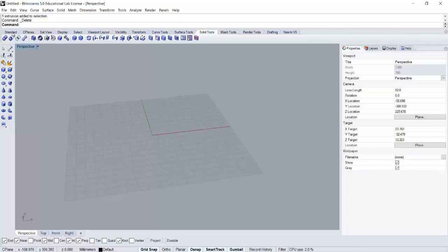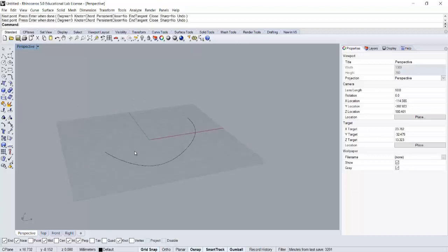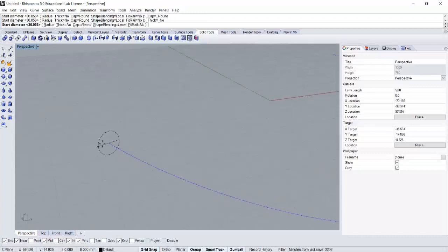Now this relies on having a curve in to start with, so let's put a curve on the floor there, and let's use the curved ends. So it says select curve, and it automatically starts you on a pipe shape, a circle shaped profile that lives on that curve.